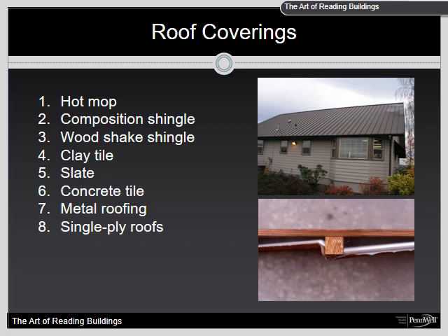Now, once fire gets into that roofing assembly, you're going to have a nightmare trying to pull up all the different layers to get to it and do in terms of salvage and overhaul. The fire spread is just unbelievable. And of course, with those multiple layers underneath, made of different types of polymers and plastics, you're definitely going to run into the release of those toxic gases that can always be present.